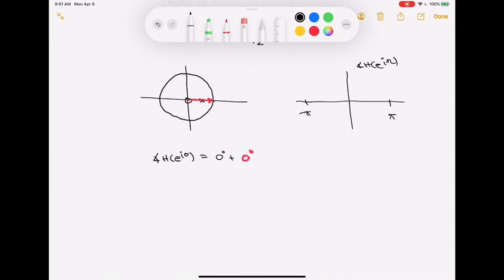If I go ahead and think about the pole, that's the thing I'm going to subtract off, minus the contribution from the pole. That thing also just points straight off to the left to get me to that DC point. And in that particular case, the angle that makes with the positive real axis is also 0. And so if I add all of those together, I do get just indeed a 0. So I get 0 in this particular case at 0.